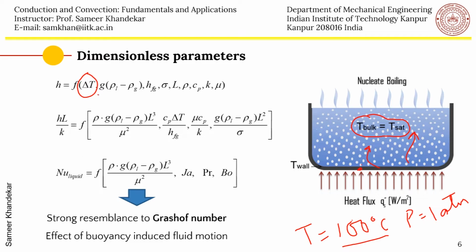Then there is a latent heat because phase change is happening. If you recall our pressure enthalpy diagram, this is the pressure, this is the enthalpy, and the saturated liquid is getting converted to saturated vapor. So this is the vapor point, this is the liquid point here, this is the liquid line, and this is the vapor line here. Therefore the latent heat is the change in enthalpy of going from saturated liquid to saturated vapor. And then there is surface tension, because with the formation of the bubbles you have interfacial phenomena taking place.